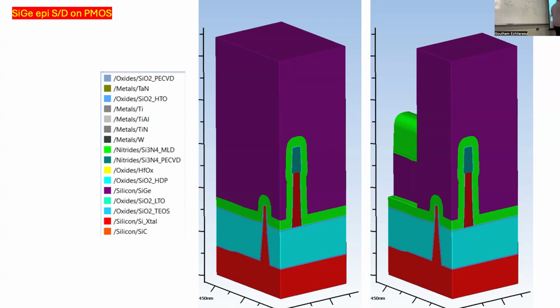Yeah, so I got a little lost. We did the oxide deposition, we did the nitride deposition, and now we're doing a silicon germanium growth. Yeah, see, basically, if I was to draw the planar case, say this was the PMOS, this was the NMOS. I know where it is. My question is, when you do the silicon germanium growth, you're already doping it, whatever heavy you dope. Yeah. You're growing it. And then we cut it, so it's a reductive process. You grow one, cut half, and you grow the other.